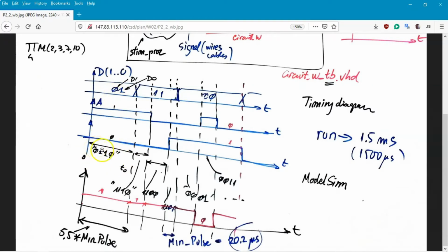Okay, and what are you expecting? Well, the simulator has to generate a 1 for the W signal. A 1, because you know it's not in the list of max terms, but is a min term. The 6 is a min term. So this is what you are expecting. The same for the next vector.